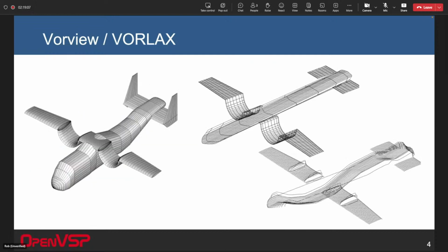But when you would apply it to more complex cases, it would sometimes become unruly, as it would do this smashing process. If you wanted to keep the camber surface, that would keep some tangent angles like this. But you would often end up with nasty gaps between the wing and the side of the fuselage. And these nasty gaps would wreak havoc on the solution.